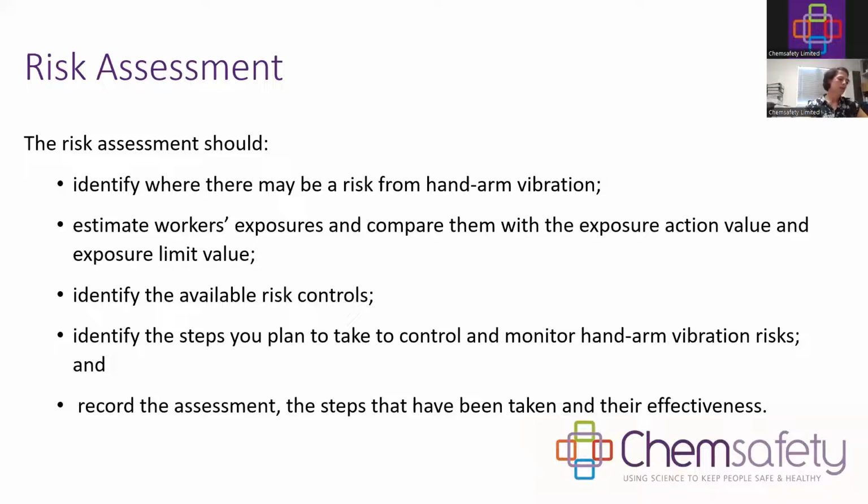And then questions that you can ask to decide whether you need further action are: what type of tools are being used? Do you use rotary action tools like grinders or polishers, or do you use impact or percussive tools like impact hammers or pneumatic impact wrenches? With impact or percussive tools, the levels of vibration are likely to be much higher than rotary tools, and some hammer action tools can exceed the exposure action value within a few minutes. So it is important to note what type of tools you have at your facility.